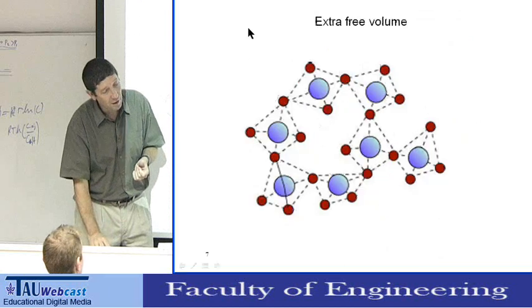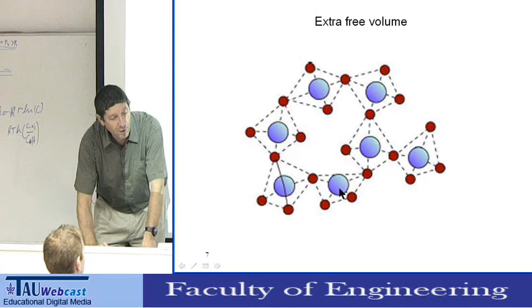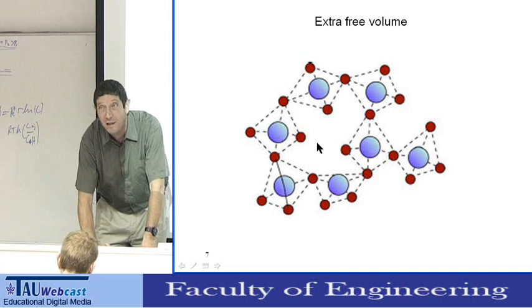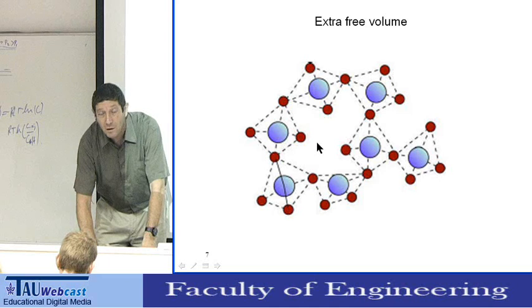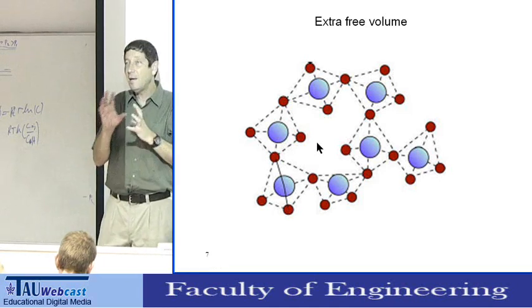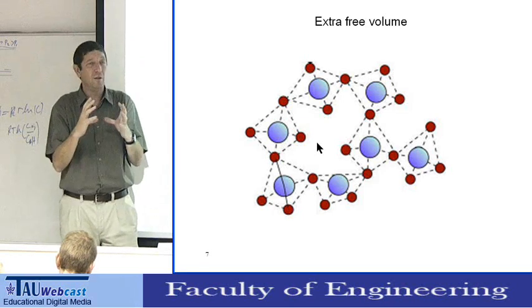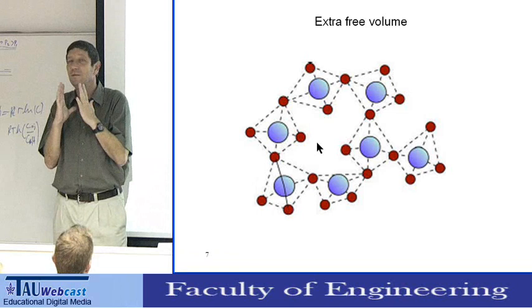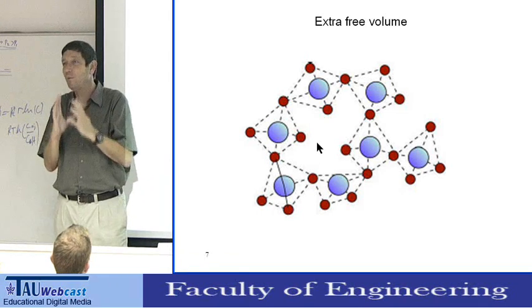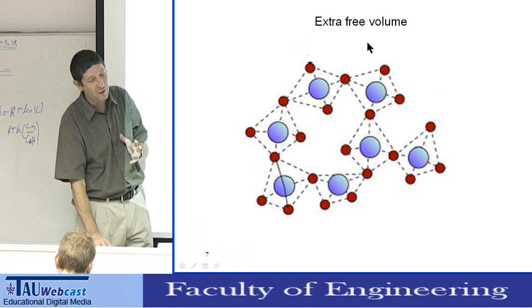Remember this fact. Now, because it's an amorphous structure, you can have, for example, one tetrahedral connected to another one, connected, and then you have a free volume inside. So, typical thermal glass has some nano-sized volumes inside, some free space inside. So it's not in the densest possible structure. So you have some extra free volume inside the glass.